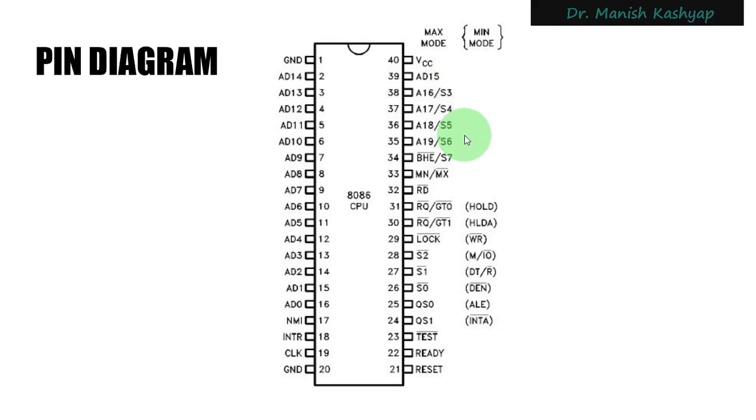But you see the beauty of multiplexing these address and data lines. If it had not been the case, then in the 8086 CPU, the design would have been complicated. You would have to make a bigger IC, and the number of ground pins would also increase. The cost would also increase. And the point on which they have been multiplexed is that address lines are seldom used in comparison to the data lines, right? So on that note, these address and data pins have been discussed.